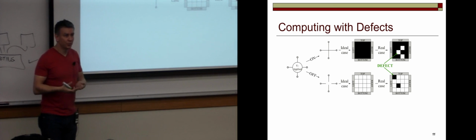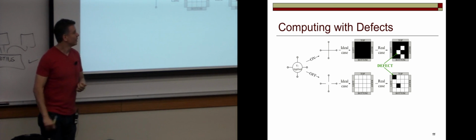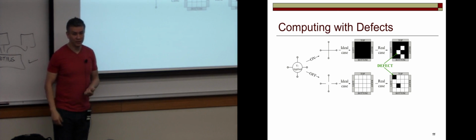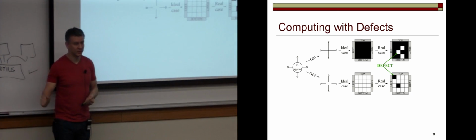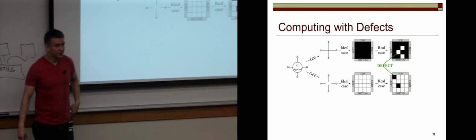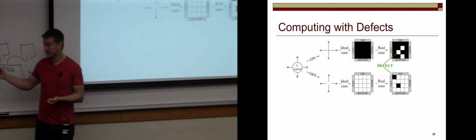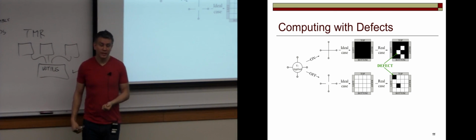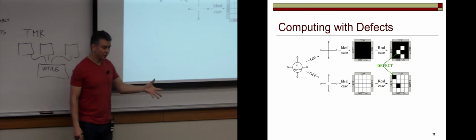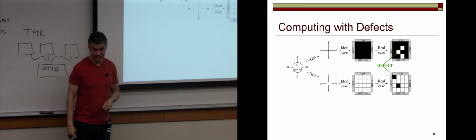So here, the permanent fault is actually very plausible. The permanent fault is that the switch is simply broken, meaning it's either permanently closed, meaning you apply a voltage, it doesn't matter, it's closed, or it's permanently open, meaning apply voltage or not, it's always open. And those are definitely the more common type of faults seen with nanoscale devices. But transient faults are very common too. That's where you have a switch that's maybe kind of working, but not working perfectly. So you look at it one day when the temperature is warm, and it seems to be working, and then it's a bit colder, and suddenly it's not.